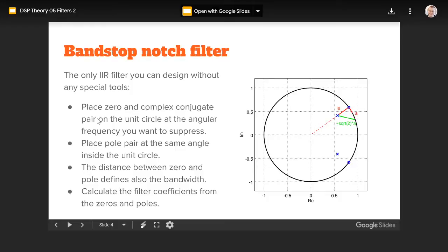It works as long as we have a perfect world. Like this is really exactly in the same place. Okay, the narrower the filter is, the less tolerance it has for time jitter, either on this disturbing noise signal. Well, if it's from the electric outlet, this is pretty good actually. I think it's 3 ppm or something like that. It's pretty constant.